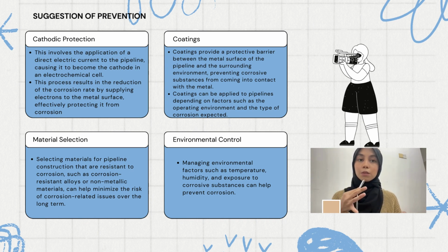And removing oxygen from the fluid reduces corrosion. When you reduce ion concentration, it decreases the corrosion rate. And lastly, when you add an inhibitor, it acts as a retarding catalyst, which also helps reduce corrosion.